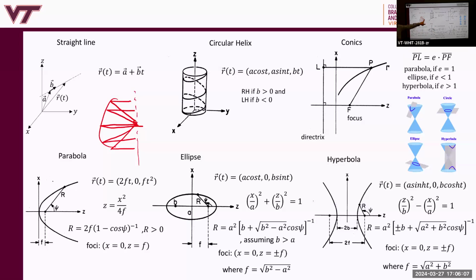So let's assume that this aperture plane is nothing but the directrix, right? And then you have your exact same thing, so the parabola has eccentricity equal to 1. So that means the length from the focus to the reflector, or the length of the focus to the curve, parabola, is equal to the length of the ray from the parabola to some aperture. Call it the directrix here, but if you put this in front, then it's the aperture plane, right? So that's the same property.